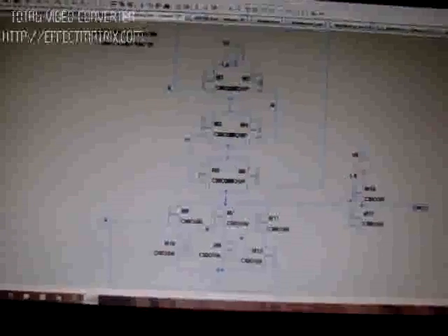Now this is the carry save adder, where we have used full adder circuits and carry generator circuits. Full adder circuits have this diagram, and carry generator circuits have this diagram. Carry generator, as we all know, AB, BC, CA. Basic diagram with an inverter here. We will get a carry before the summer generates the sum, so we can easily reduce the time for our implementation. So I'll close all that again.